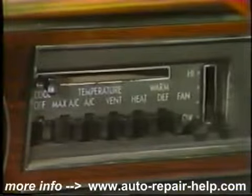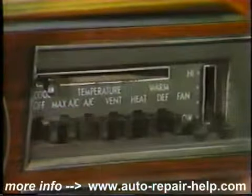Move the control through each mode with the blower on high. Place your hand over each related air vent and check the temperature and volume of the air.